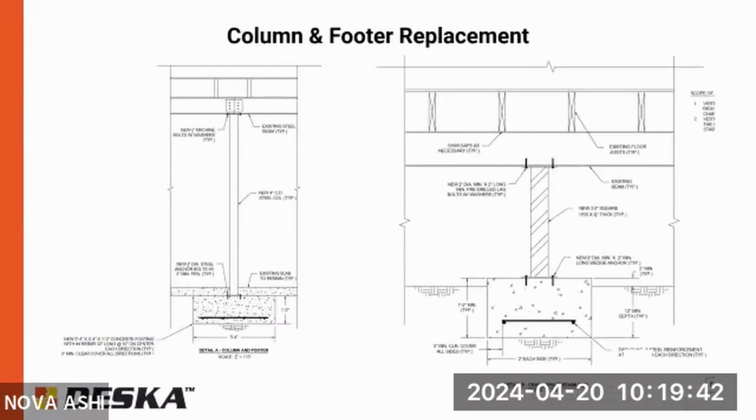Here's an example. In this case, there's your 12 inches in a crawl space. If it was on the exterior, it would need to be deeper in this area. This is a crawl space example, and then we have more of a basement example, both supporting, in this case, steel beams.